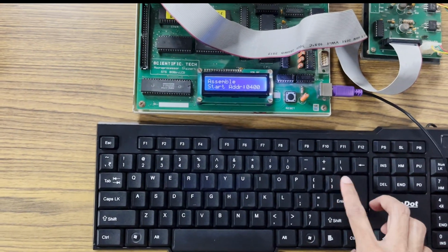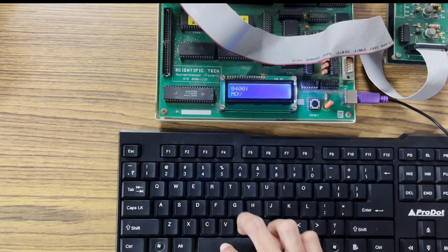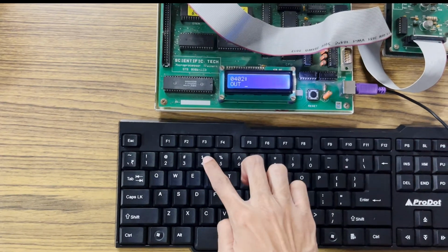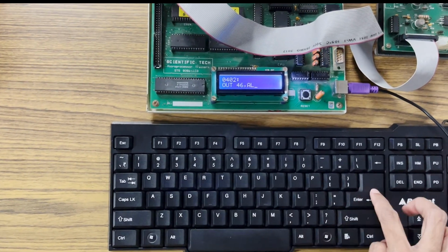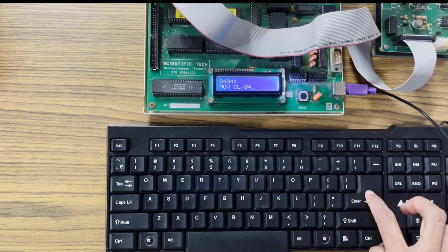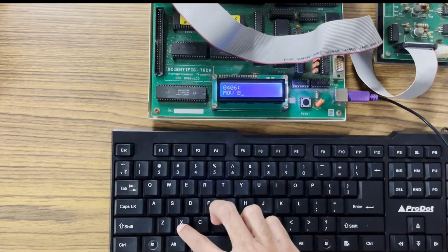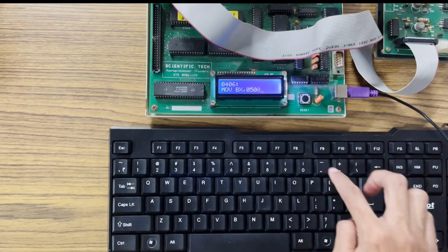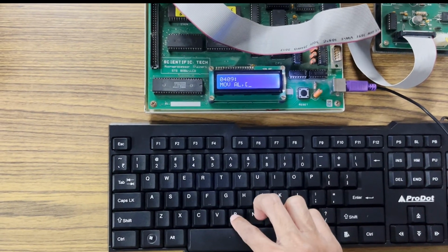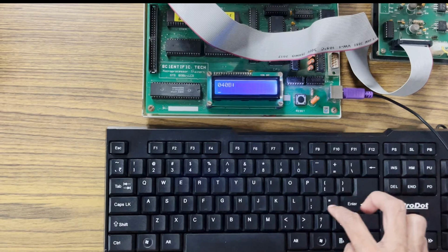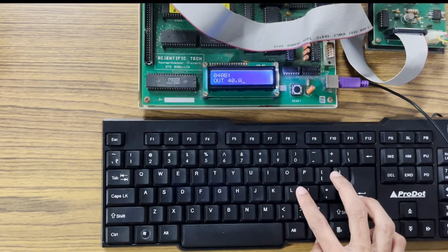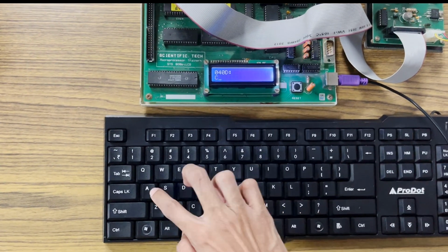Now, as in the usual case, we will be writing this program to the particular location 0400, starting by setting the control word register, and putting into the location 46H where we have our control word, setting the counter as 4, as we are repeating this set of 4 steps in an infinite loop. Then we are loading the address where we will be feeding the data, which is 0500 to BX, and then we access the value from the location of BX to AL, and we take each of these values and place them in the output IO port of 8255.